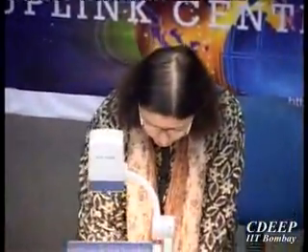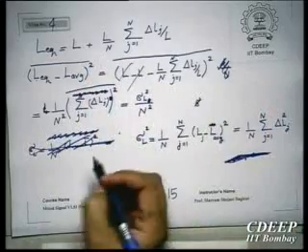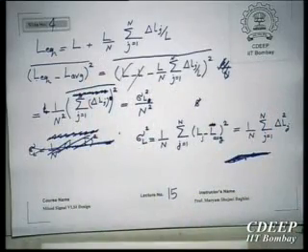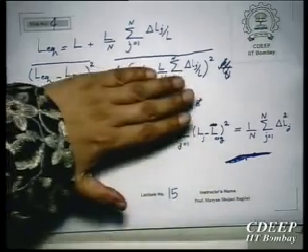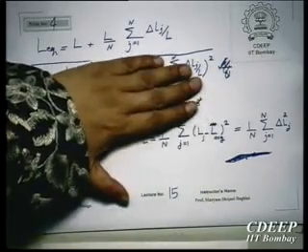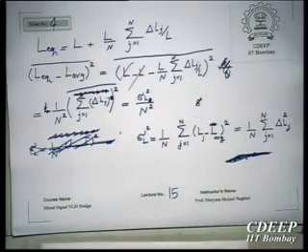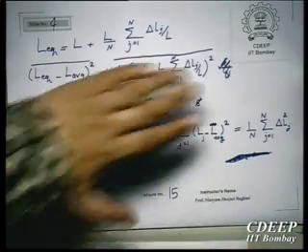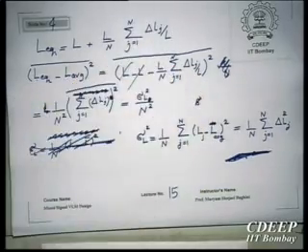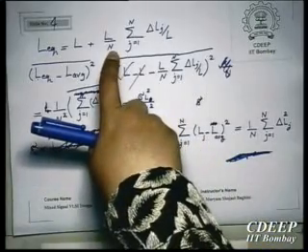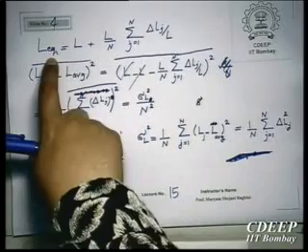See, L average is the average across all n strips. You have n parallel transistors with different L's. Average of all these L's, we call it L. L equivalent is this. I will check it next time and tell you. Don't be so concerned about this part. You just forget this part. Just look at this: if you increase the number n, effectively your L equivalent approaches L.